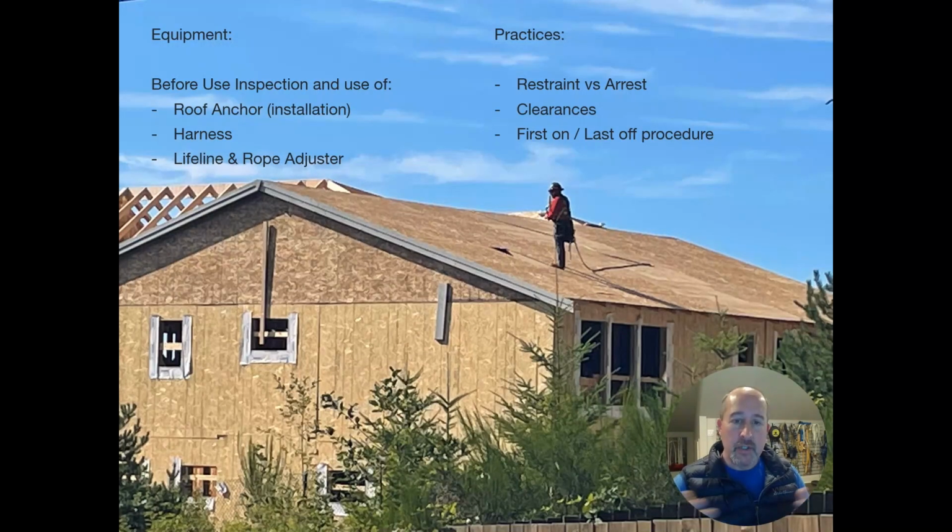Following the path of the worker and documenting all of the equipment that they're going to be exposed to. First of all, if they are installing their own anchor, there's going to be the anchorage connector, whether that's a nail down, lag down, pass through, however that anchorage is going to be installed. If they are installing it, there should be an experiential exercise during training, even if it's simulated on the ground with a couple of chunks of wood, how to install that anchorage connector.